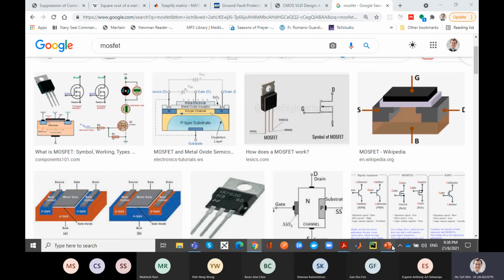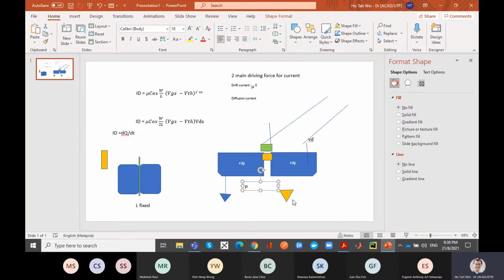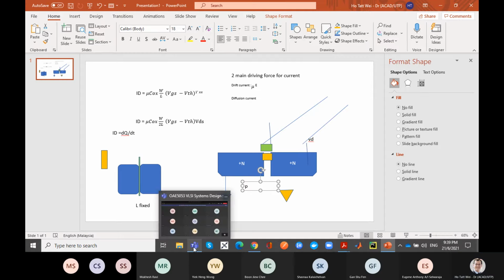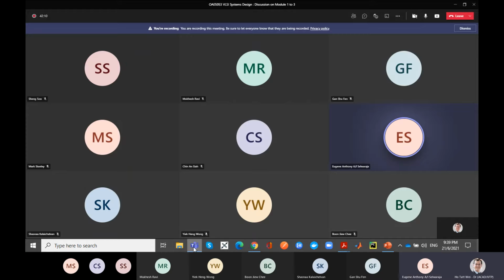Okay, that is module 3. I'm all about telling you the effect of module 3, more or less what its approximate value is. Roughly, when we do logical effort later on, we're going to take the capacitance here and the capacitance here to be roughly the same as the gate capacitance. It may change with future technology. That one you can check with the fab, but this is just for you to understand where it comes from. Okay? Yeah, great. I just need to make sure you get that.